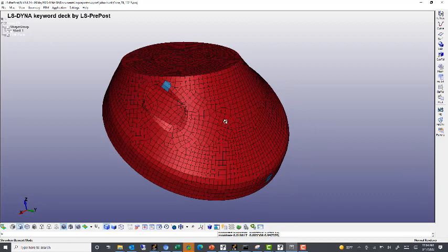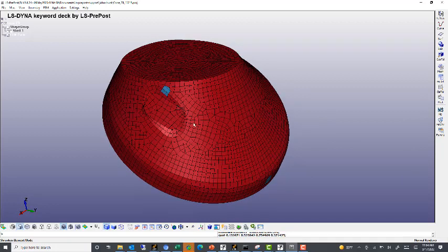So the first thing we like to fix is to move those elements into the same layer instead of spreading across 3 different parts. If I go up here, you can tell we have shell 1, which is the default one, and these were probably created by the user when they create a new element and patch up some failed element.